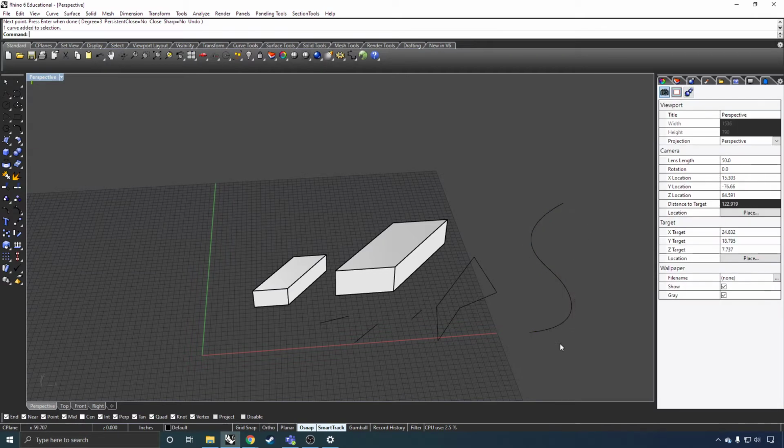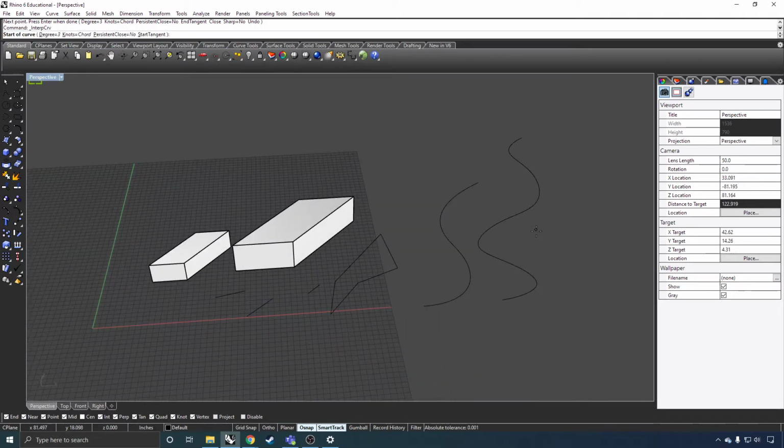I use the interpolate curve whenever I'm inside Rhino. So if I click on this arrow here, you'll see this one, interpolate curve, my mistake, where you have these 4 points, but they're not outside of the curve, they're on the curve. This forces it to be on that point. You'll notice it can get wonky as you get closer to it. But generally, if you're tracing something like a contour, this is easier. You just have to drop more points occasionally.